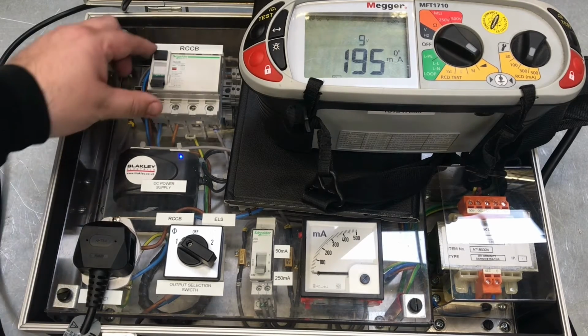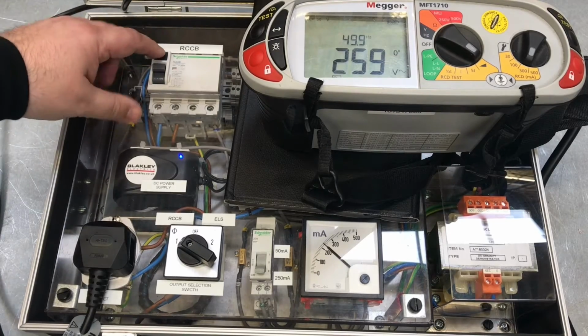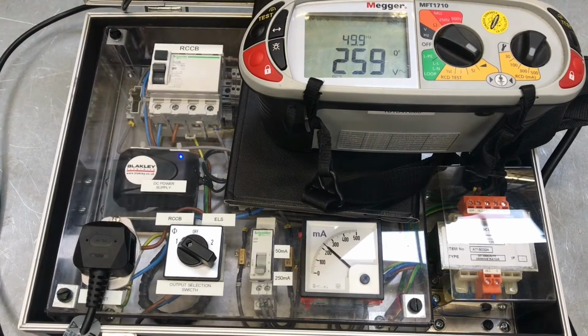So this is a real serious problem. It does not trip. It saturates that magnetic core. It interferes with that sine wave. So the easiest way I've ever explained it, and I actually did this in my chartership interview, was I said to the chap interviewing me, I've done a lot of research on how DC affects RCDs. He went, well, how does that work? To explain how an RCD works, I said to him, well, I'll give you the detailed version and the simple version. And he said, okay, I'll have the simple version.